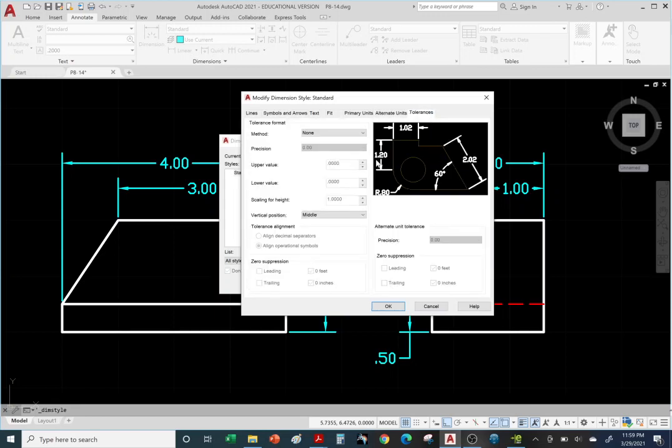And then we have tolerance. Okay, so tolerance, we're going to talk about tolerance in a separate chapter. We'll dedicate actually 2 chapters to tolerance. That's how much wiggle room you're going to give the machinist on how much they can be off by. So if you go to a Home Depot or Lowe's and you need a 2x4 and you ask the person there that cuts the 2x4, operating the saw, hey, I need a 2x4 5 feet long. You have to give them some wiggle room how much they can be off by. So they'll probably say, hey, is it okay if I go 5 feet 1 inch? Obviously they have a nice ruler there that they can use to be more precise, but you want to give them a little bit of wiggle room.